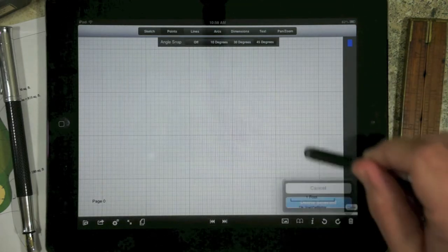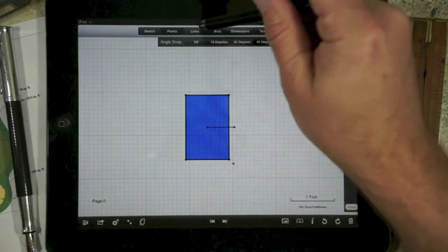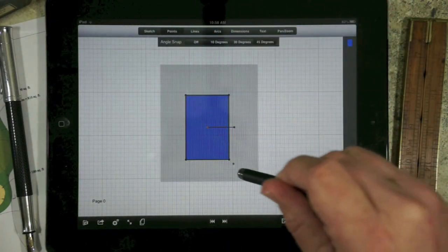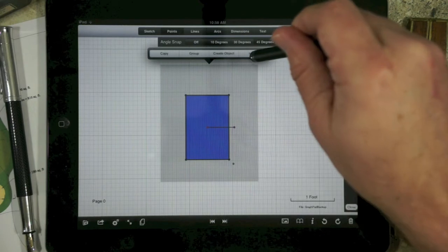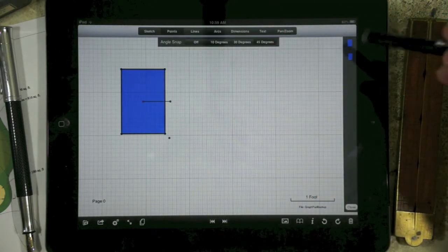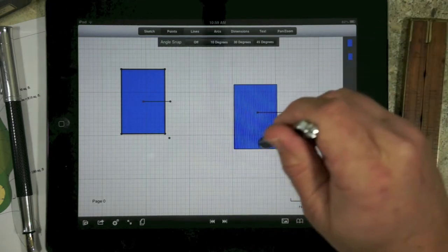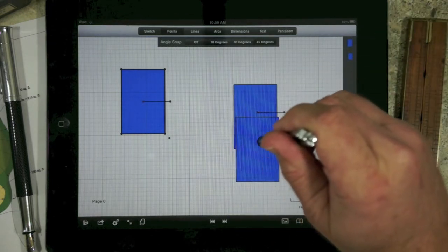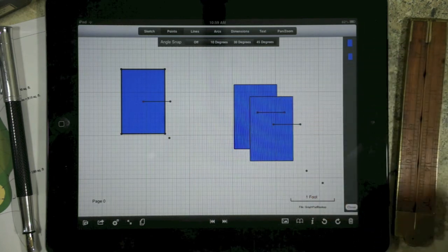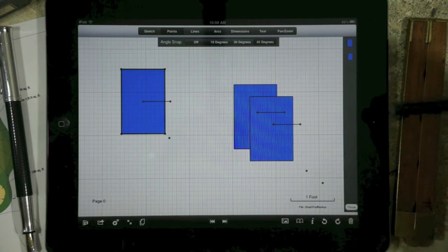Now, in addition to that, we also have the ability to create an image. So we'll take the same item, we'll select it, and now we'll create an image. The difference between an image and geometry is that images stack. So if we put two images on top of each other, we'll notice that it's an image, it's stacked on top of it, so you see the top image and not the bottom image wherever they cover.